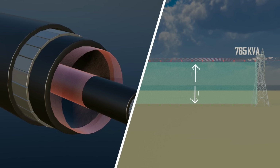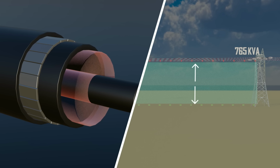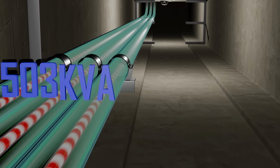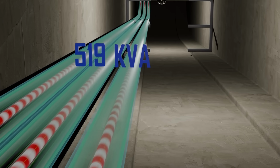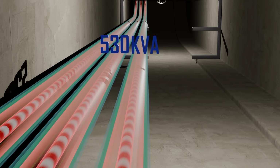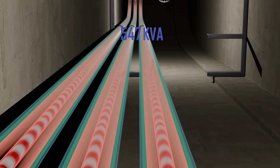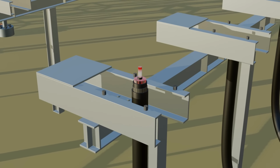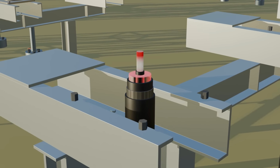In an overhead line, there is a much greater distance between the conductor and the ground, but in a cable, only a few millimeters separate the conductor from the metallic screen. As a result, the receiving end voltage can rise significantly. If the cable is operating under no load condition, this capacitive interference can become even stronger. But cable insulation is designed for a specific voltage range, so when the voltage rises beyond that limit, the risk of insulation damage and faults also increases.